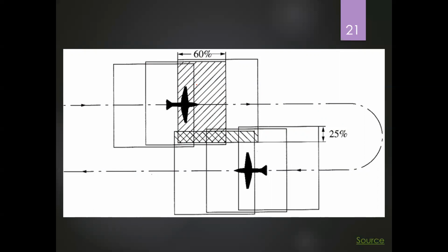When you are doing georeferencing, when you are doing geometric correction, you need the overlapped area as reference, which means this area appeared in at least 2 images. So you can find the same location in 2 images to create the relationship between a specific location in the real world and that location in your image. That's the reason why there must be overlap.